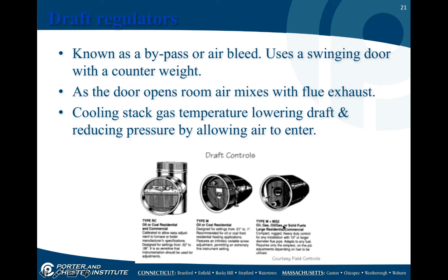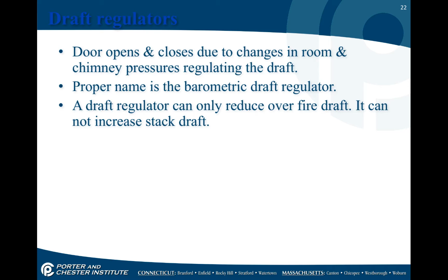Now just be aware there's different types of draft controls. You have to check code and you have to look at the equipment to make sure you have the correct one. The door opens and closes due to changes in room and chimney pressures. So that's why the weight is there.